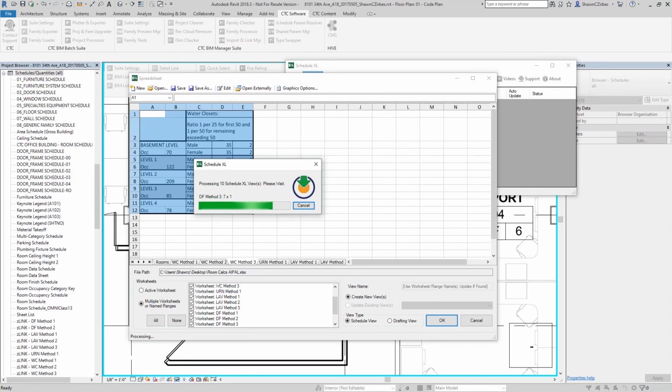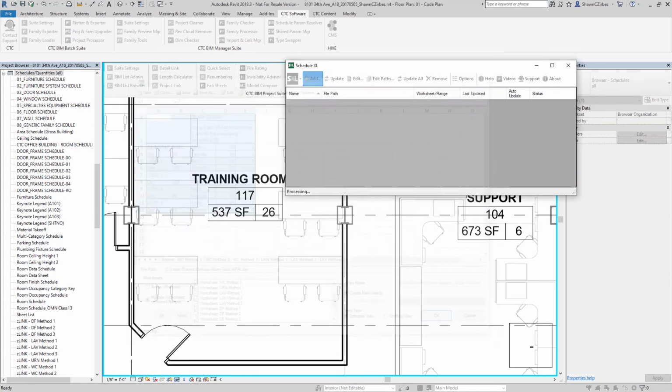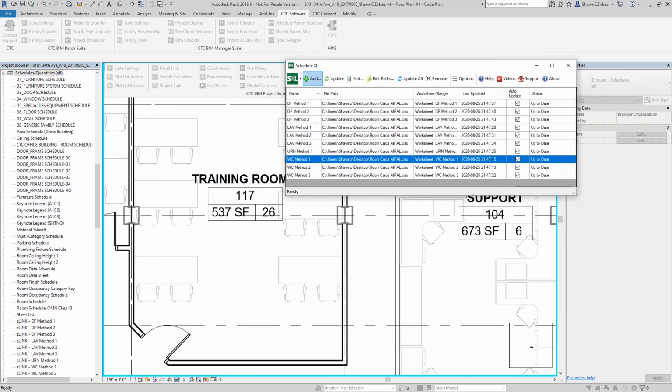And every time there's a change, you have to save your Excel file, open and save the AutoCAD DWG per each tab you're bringing in, and then go into Revit and refresh all those links. That's all manual, right? This just did it, and it's going to keep it automatically up to date like every other link in Revit would do. So a fantastic, easy way of getting those Excel tabs brought in.